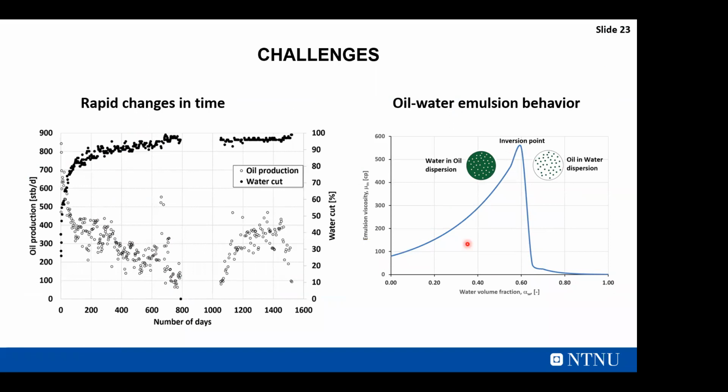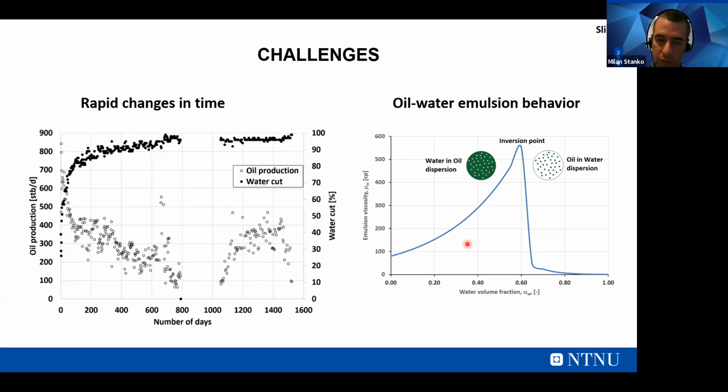Okay, something else you mentioned at the start of the presentation is that you did not treat the interaction between the reservoir and the wellbore thoroughly. Which model did you use for the interaction between them? Is it a simple one like Vogel? No, at least in this case, Rubiales was undersaturated, so we were using just a linear PI, but the PI was changing with time, as was the water cut.